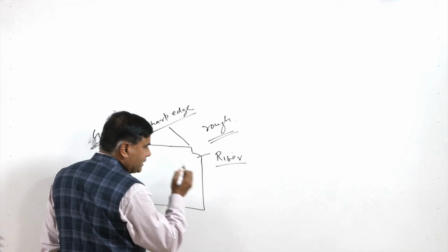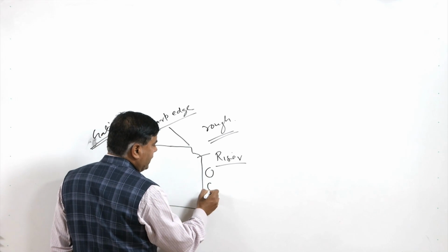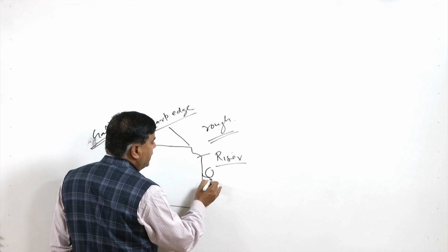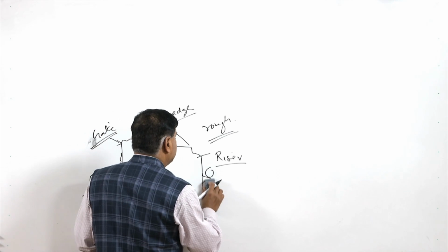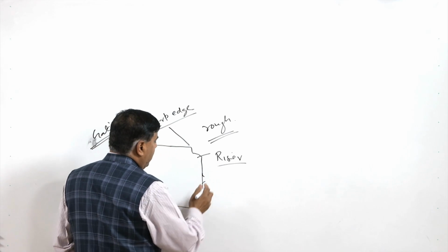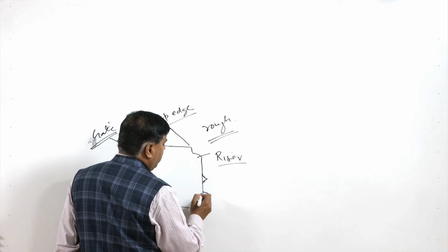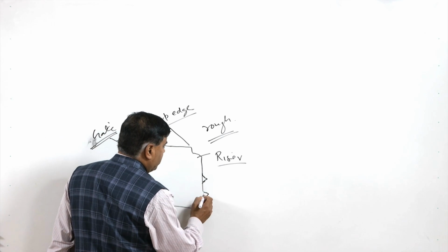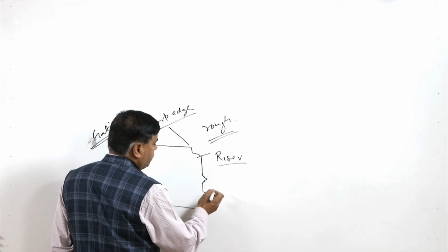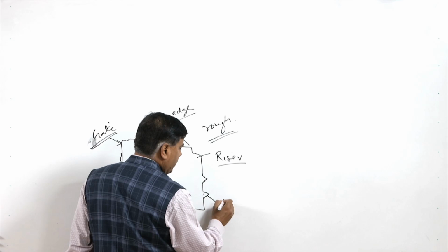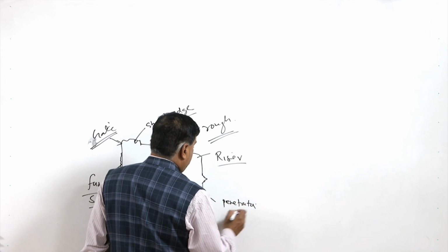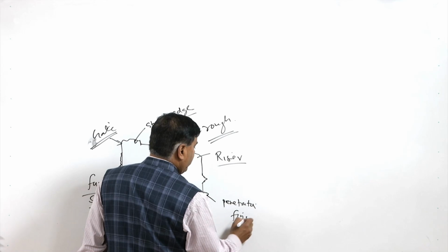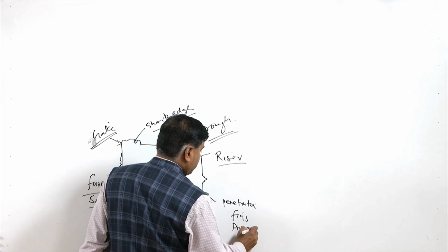If the sand mold had coarse sand particles, then the molten metal will penetrate in those regions, and we will see that very fine projections of the metal are present in the casting. So, these fine projections also need to be removed.